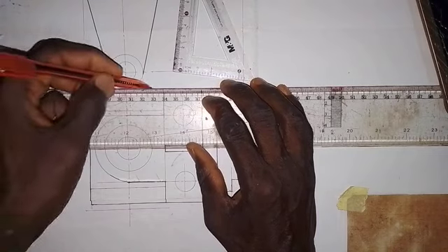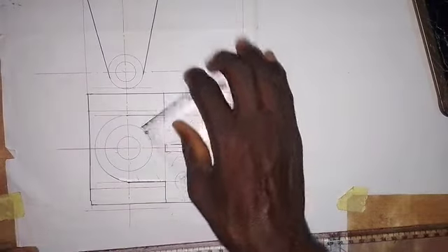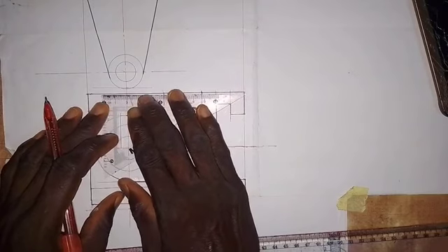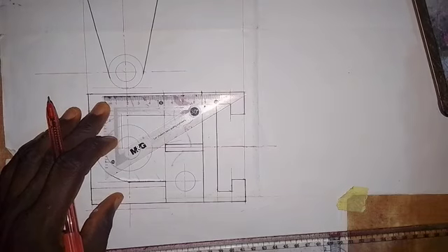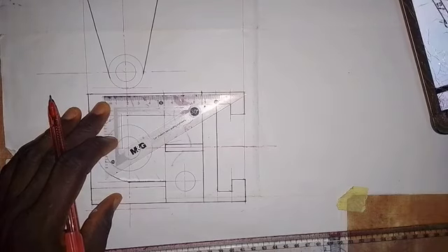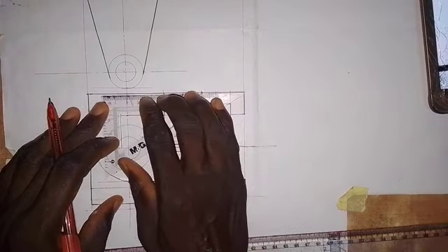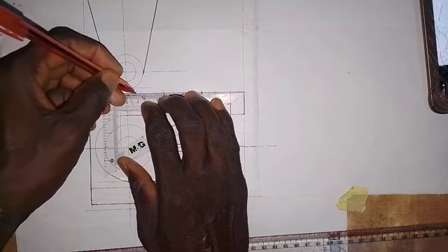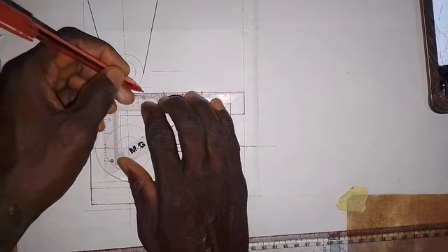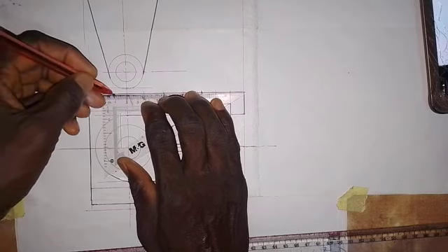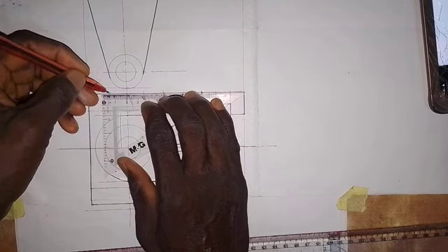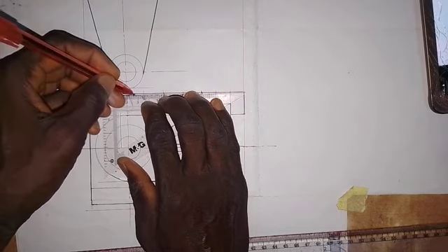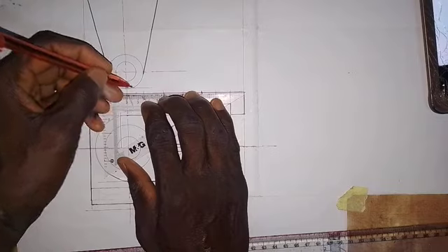We have this. On the external part, we have the diameter of the big circle to be, let me check, I think the diameter is 30. So we take 15 from here to this side. This is 15 millimeters, and from this point we also take 15 from here to this side. The inner one, the diameter is 18, so we take 9 millimeters. This is 9 millimeters here, and then here we also take 9 millimeters to this side.